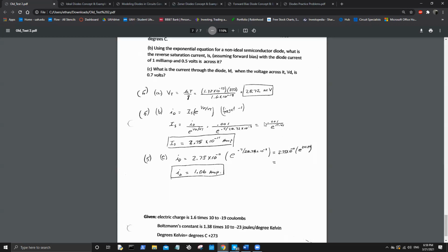But also fundamentally, it's interesting because in 310, taking it beforehand, you'd see a question like this and be like, why are they asking us to calculate IS? It's just a constant. But it makes sense because in the real world, IS isn't a constant. Saturation current can change diode to diode, material to material. It's not one size fits all. So that's cool to see.